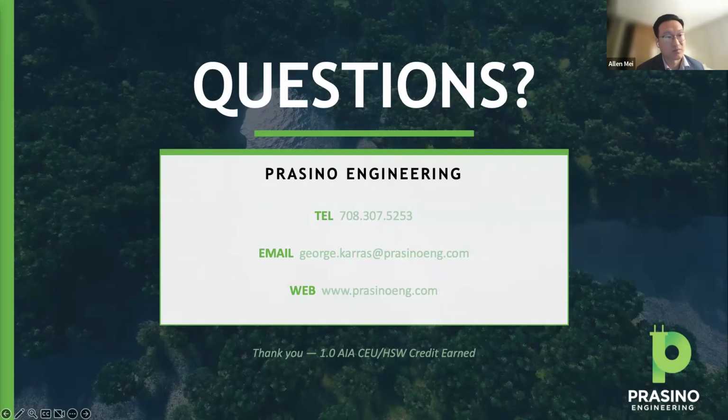on-site renewable is a mandatory requirement. You either do on-site renewable, like actual PV, or a power purchase agreement. There is no way to get out of it. So generally, IECC made more things mandatory and less flexible. That's why IECC is generally more stringent, a little more difficult to comply with, I would say.